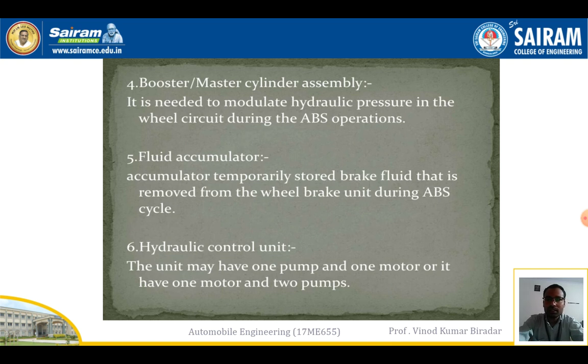The fourth one is the master cylinder. This master cylinder part is very important. Almost all braking systems use master cylinders. It is needed to modulate the hydraulic pressure in the wheel circuit during anti-lock braking system operation. Next one is the fluid accumulator. The accumulator temporarily stores the brake fluid that is removed from the wheel brake unit during anti-lock braking system operation.